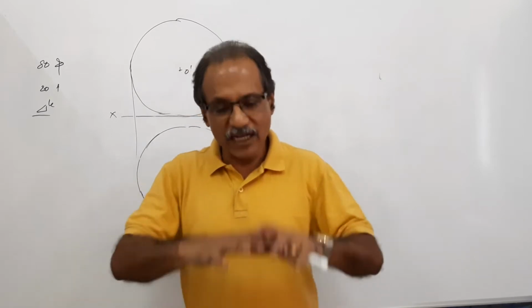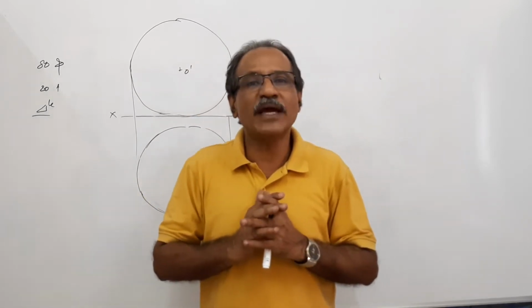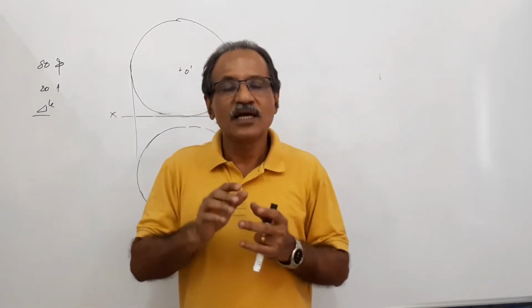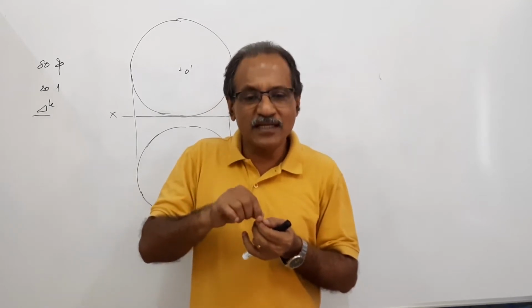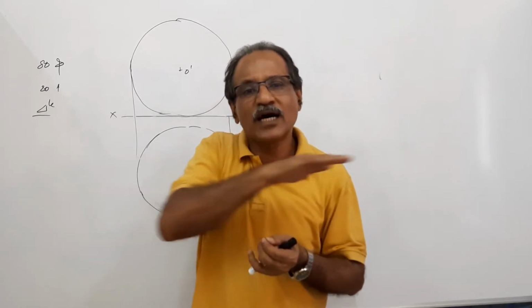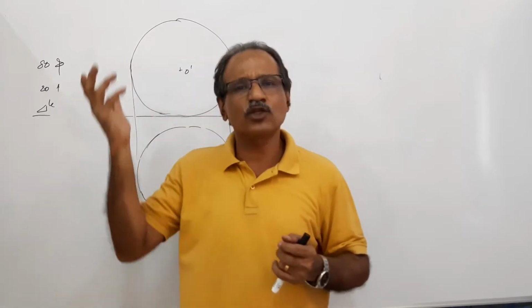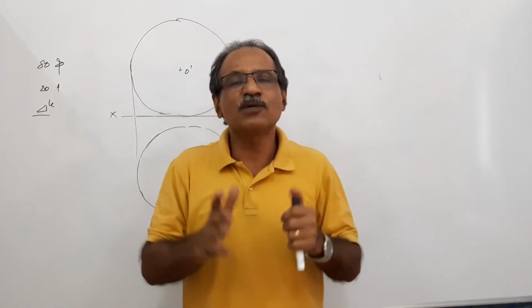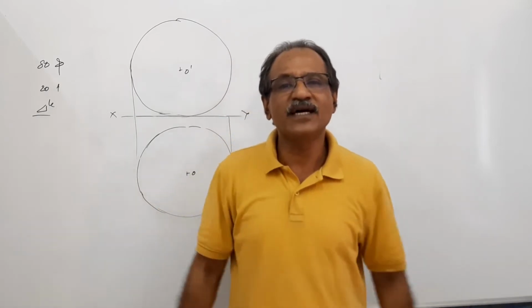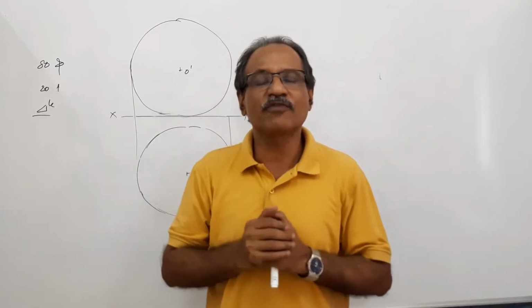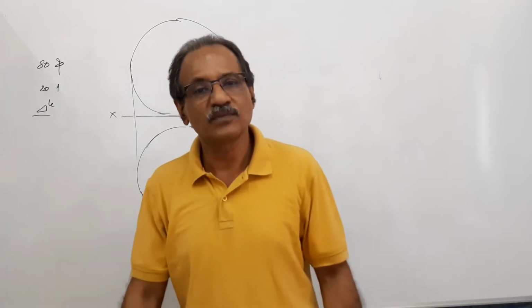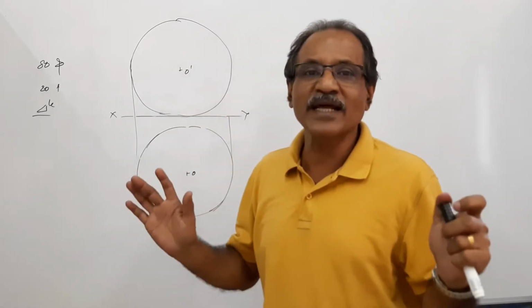I repeat. A sphere is resting on the ground, 80 mm diameter, 40 mm radius. It is cut by a horizontal cutting plane passing through 20 mm above the center. After removing the small portion, the largest possible equilateral triangle is inscribed in the cut circular face. Draw isoprojection. Agreed? Okay. We have to draw plan and elevation.